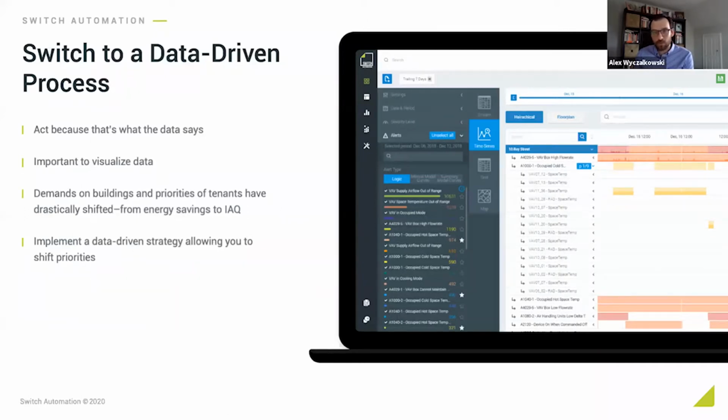So before, we used CO2 for tenant comfort, and we may measure CO2 and say that 1,000 ppm, parts per million, is appropriate for tenant comfort. Well, we're maybe worried about building health. So a metric that I'm seeing that shift to is about 700 parts per million.